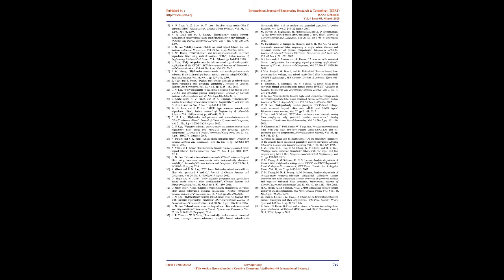Fig 3 presents the simulated bandpass, lowpass, highpass, notch, and all-pass amplitude frequency responses of the proposed general mixed-mode biquad filter, operated in TAM with the normalized transadmittance magnitude = 20 log10(10,000 Iout/Vin) dB due to R = 10 kΩ. Fig 4 presents the simulated all-pass phase frequency responses of the proposed general mixed-mode biquad filter, operated in TAM. Although not included in this paper, it can be shown that the other modes' simulated results, with the normalized magnitude, are very similar to the above simulated results. As can be seen, there is a close agreement between theory and simulation.